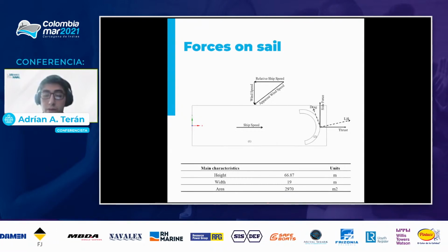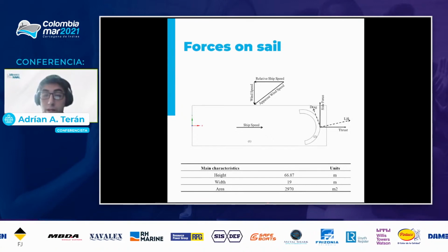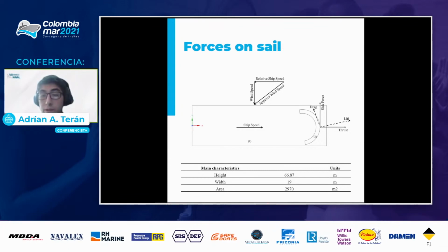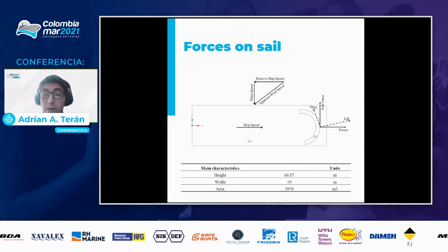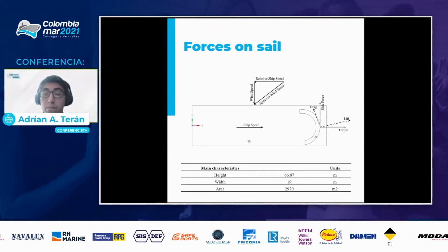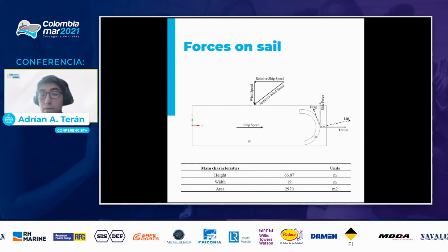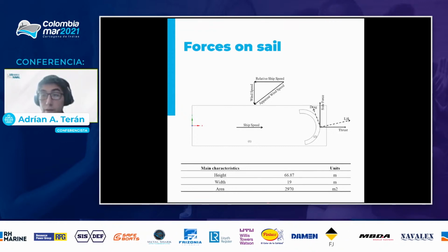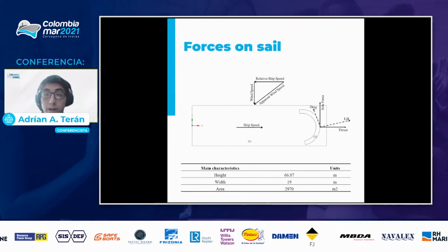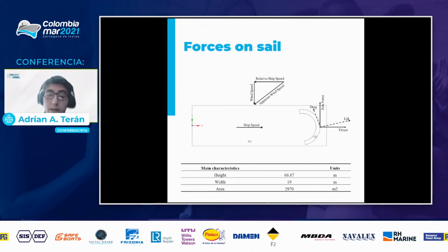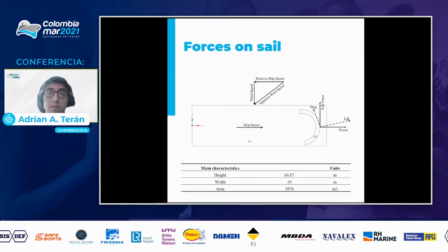Now, as we consider these forces in the directions that we want to analyze, which is basically the bearing of the vessel and the perpendicular direction, we're going to be able to see a drive force that goes in the direction of the vessel and a force alongside. That is the force that gives the vessel a list.